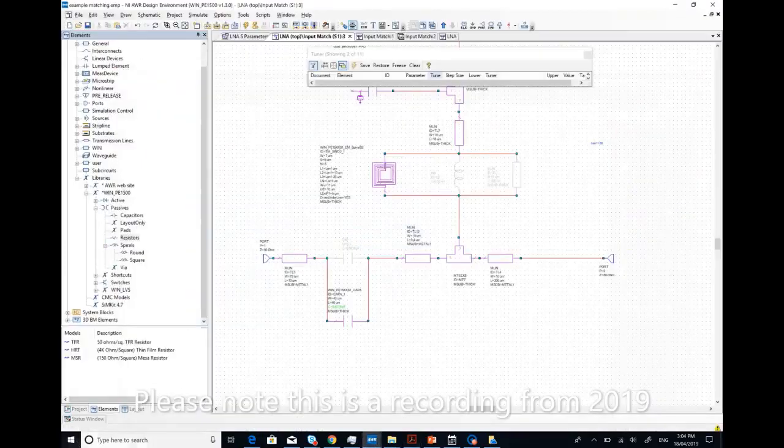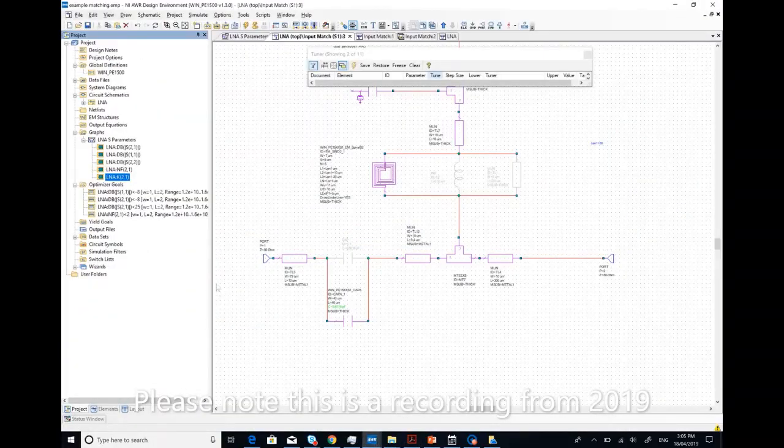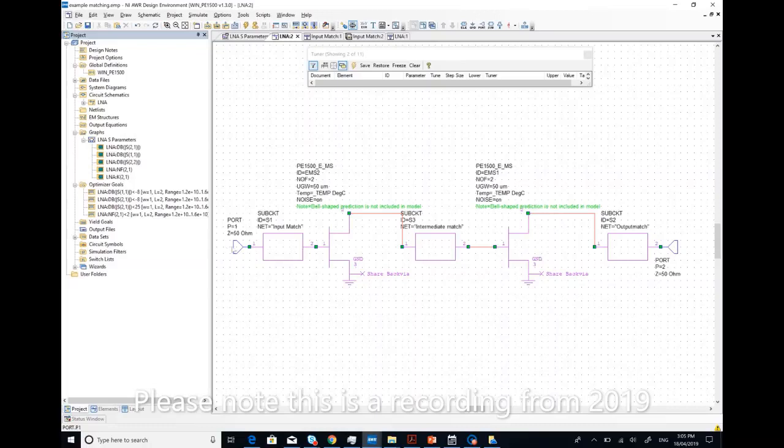Now if you want to make a PSAT, it's quite easy. PSAT is the saturated power at the output. So we input some power into the circuit, and then we look at the output power. We increase the input power levels from a lower power level to a higher power level and look at what happens to your output. It starts to go out of the linear region after a certain power level because transistors come into saturation.